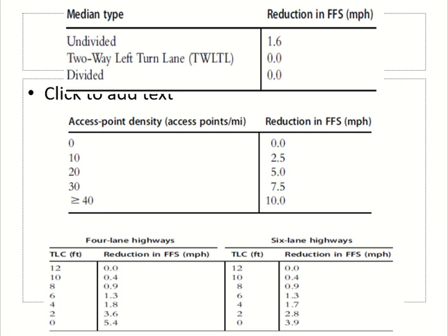So on undivided highways, there is no separation. So the actual lateral clearance on the left hand side, the median side, is 0. But the problem is, for undivided highway, we already incorporated a factor here. Okay, so we cannot put two factors, the effect of the one condition, which is undividedness of the highway, on two factors. So we already have the impact of the highway being undivided on median type factor. So you want to avoid duplicating this effect.